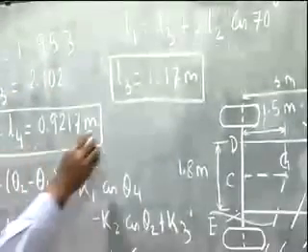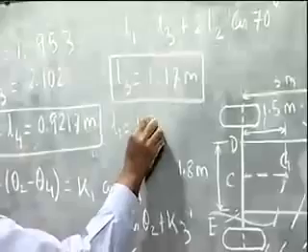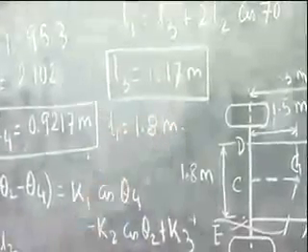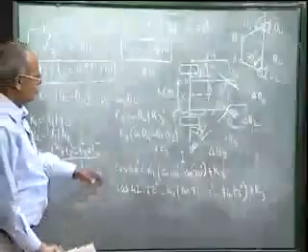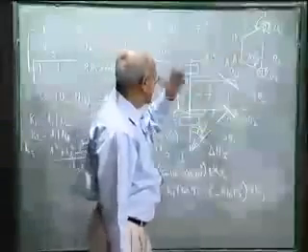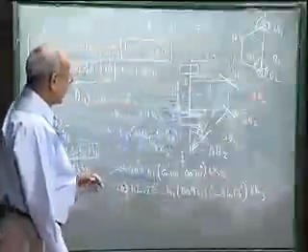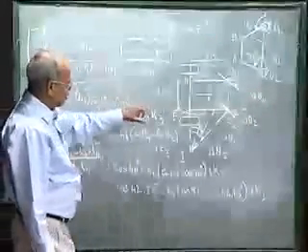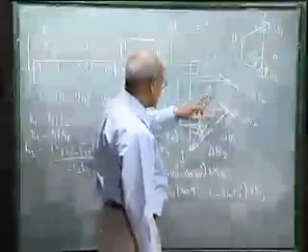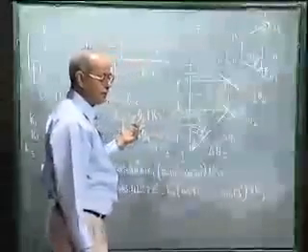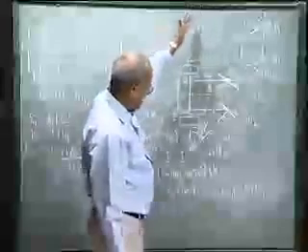So, L1 was given to us as 1.8 meters. So we can use Freudenstein's method to synthesize this Ackermann steering mechanism to satisfy the requirement that at a particular value of the turning radius for the center point G, which we took as 11.55 meters, the steering condition will be exactly satisfied. It will be exactly satisfied for an identical left-hand turn. This we did for right-hand turn, and obviously it is all right for the straight path.